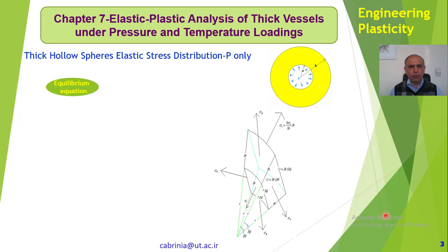First of all, I'm going to consider thick hollow spheres, and the loading in here is pressure only, okay? Internal pressure only. So we have this sphere, internal radius A, external radius B. So it's a hollow sphere, and inside it, there is a pressure loading as shown in here. This pressure loading could be due to fluid pressure which is held inside this vessel.